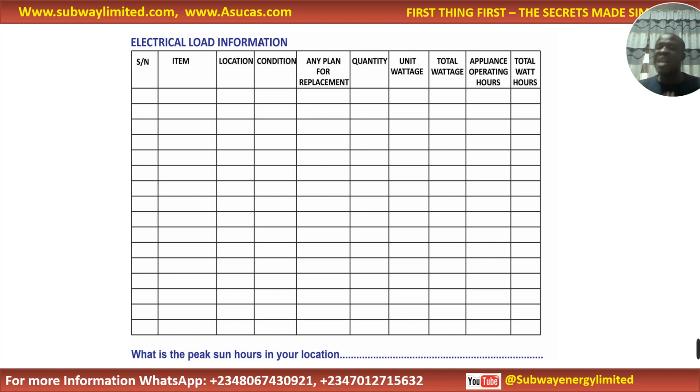So any equipment, electrical load you are seeing, please ensure that you write the condition. Those that are not working, ensure that you ask your client, sir, when I finish this power audit, will you fix this electrical load and use it? This will save you the stress of running helter-skelter when they call you that the system is shutting down. It does not last because they are using more load than what the system was designed for. So any need for replacement, if yes, you write yes. If no, you know that is out of the information you need.